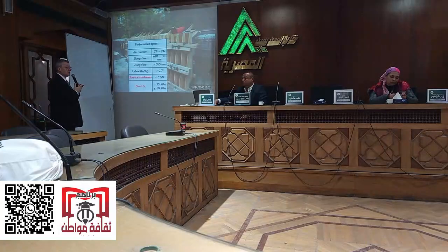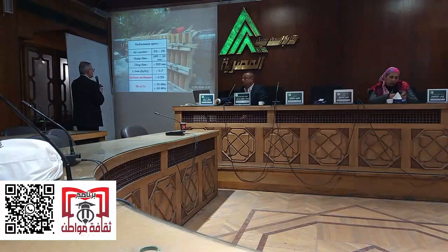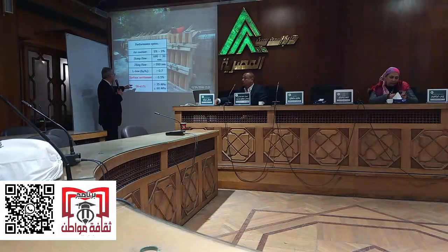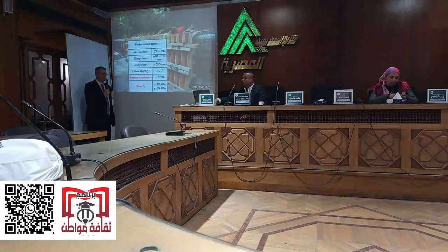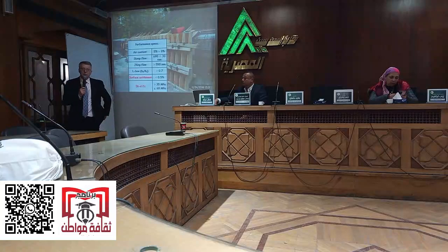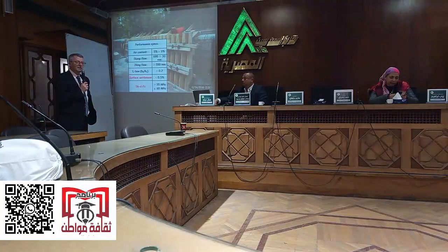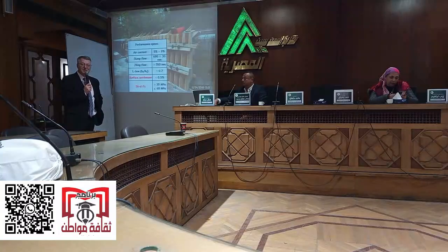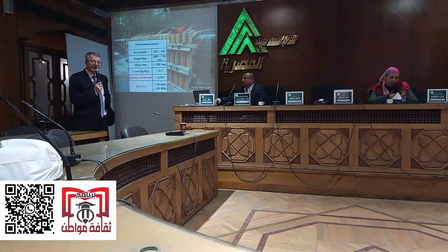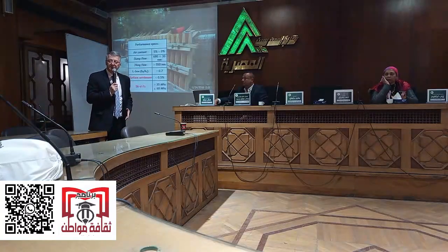The slump flow is very high. It's uniform, VSI is 0. The spread has to be at least 550. The surface settlement is a maximum of 0.5%, and for the 56-day compressive strength, you want it to be more than 35 MPa, but less than 60 MPa. You don't often see a specification of "less than." The reason is that if you make it very high strength, it cracks.